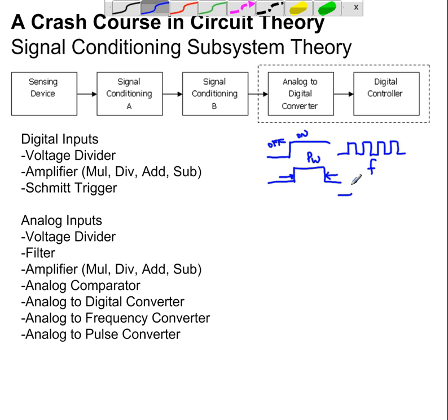And you also can read frames of data. Typically, microcontrollers read 8 bits in one frame. So you can imagine that this here is an 8-bit set of data: 01001010. So it can communicate with complex components. All of these options are available for the microcontroller as a digital input.